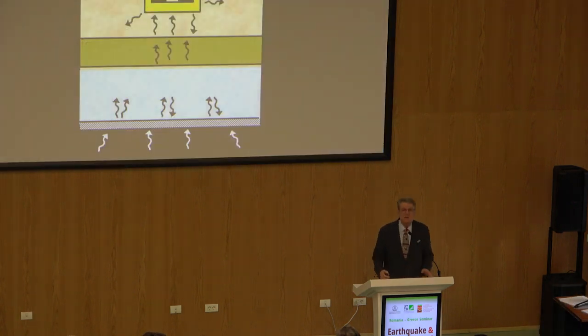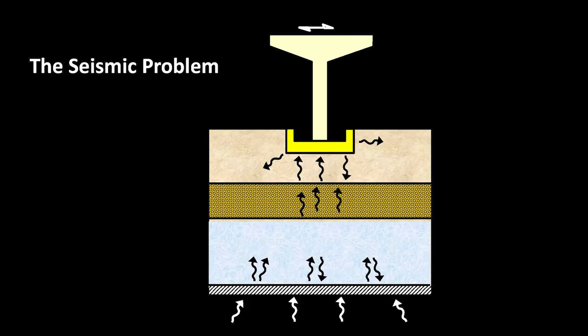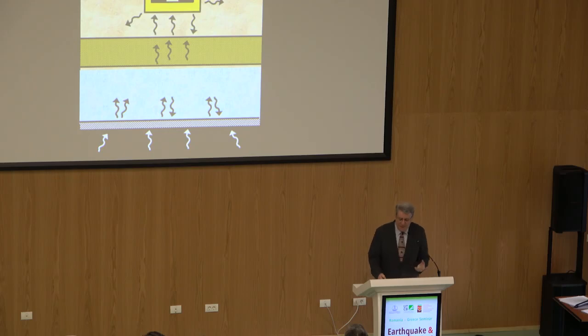So, let's start with a basic seismic problem from the geotechnical point of view. We have the structure on the foundation, which is not just a simple spring, as we usually see structural engineers do it, but it's a whole system. Here is an embedded foundation. The waves arriving from the base, not only vertical, all sorts of waves, propagating through the soil, affect foundation and structure as well.